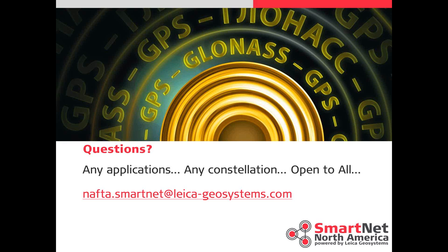Coy, I'll send it to you again. We talked about RTK Bridge. Can it help with any cell problems? What is this? An RTK Bridge is basically a radio and a modem slammed together so that you could set the unit where you did have cellular reception, or put a high gain antenna on it, where on a rover you wouldn't be able to do this, and then rebroadcast the corrections via radio. If you need more information, we can get it to you offline.